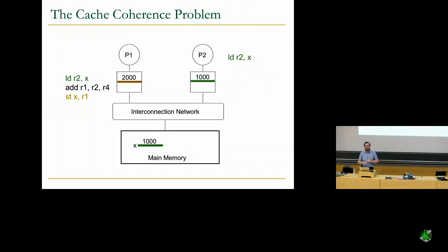The hardware could also say, oh, this processor is writing 2,000 to the block. I'm going to search all of the caches and update that block such that the value over there is 2,000 now. That's a little bit more complicated, but that's another cache coherence protocol. So you can see the complexity of this, and there are many, many design choices over here as well. So we've covered caches mainly from a single core or single thread perspective. There's a lot to do over there, but there's even a lot more to do in the multi-thread, multi-core perspective. And this is one example over here.